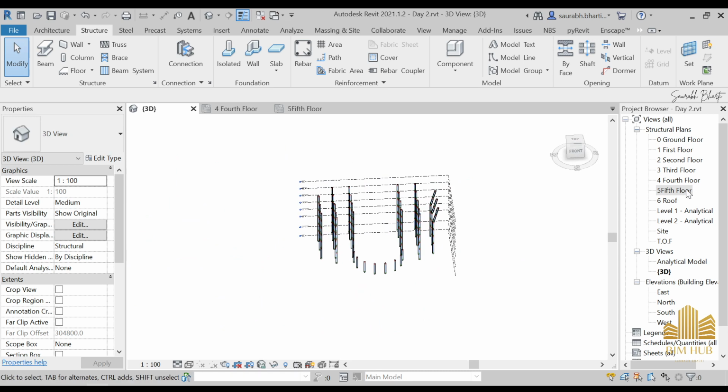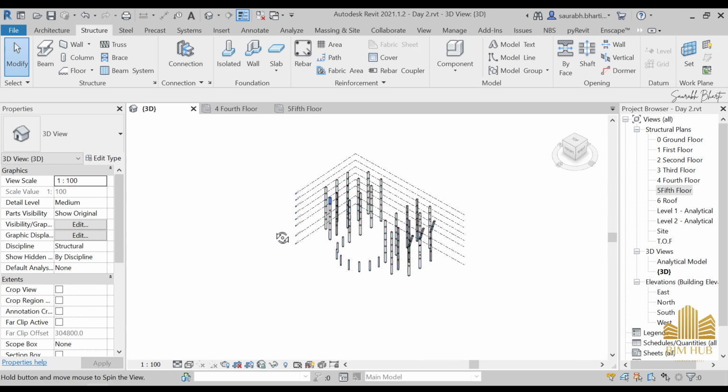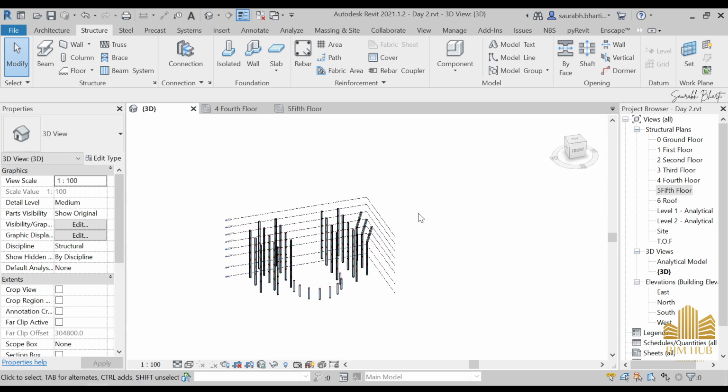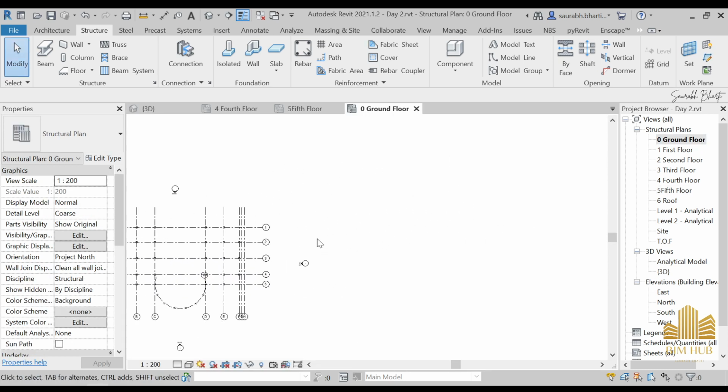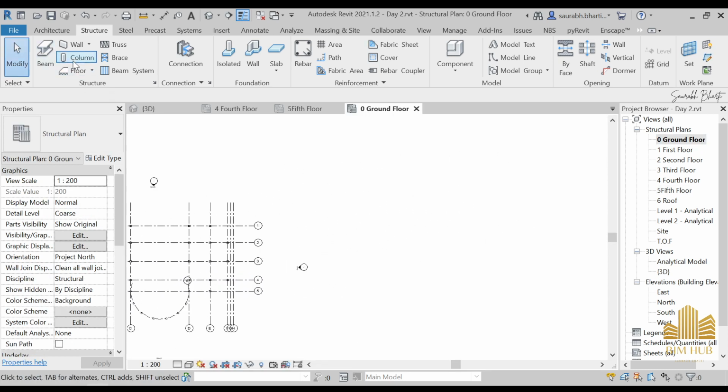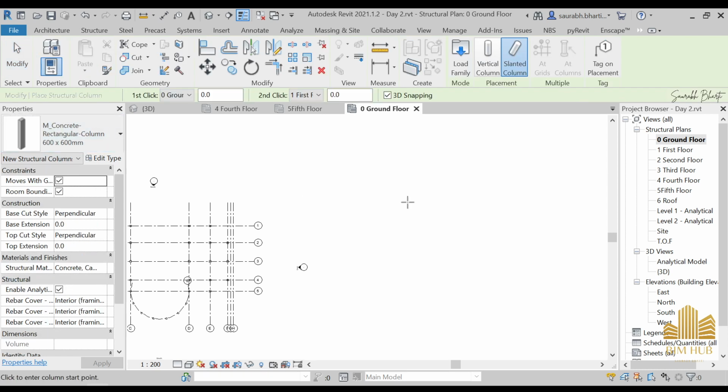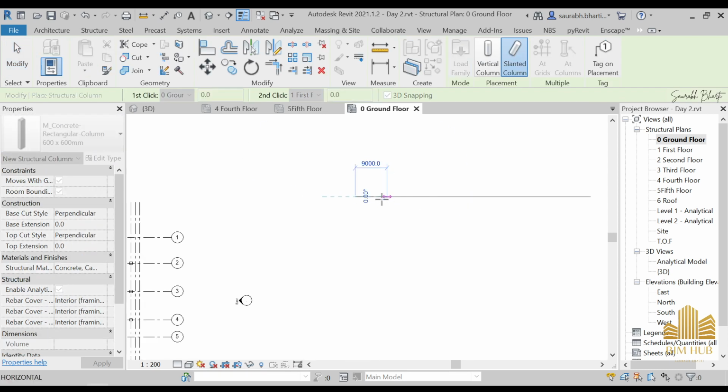There are a few more things that I need to tell you. So let me tell you first, and then I will end this session. We are done with this column section actually. I'm just telling about a few more things in column. What if I'm making this column on this side? Just go to the column, select this column, and just put one. Okay, this is slanted, just select this vertical.